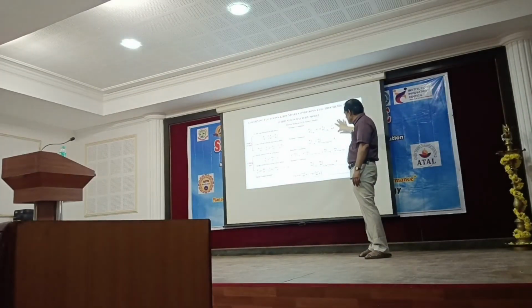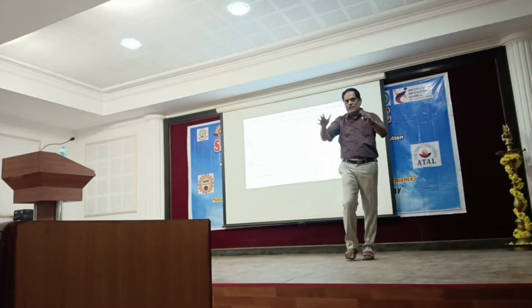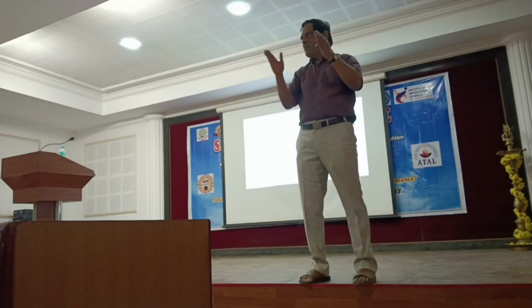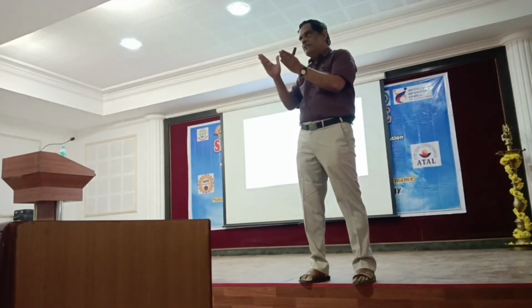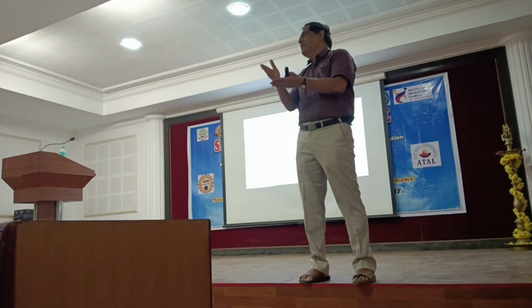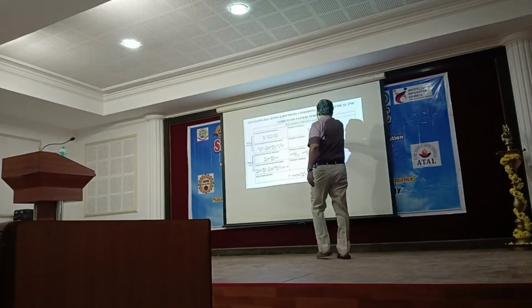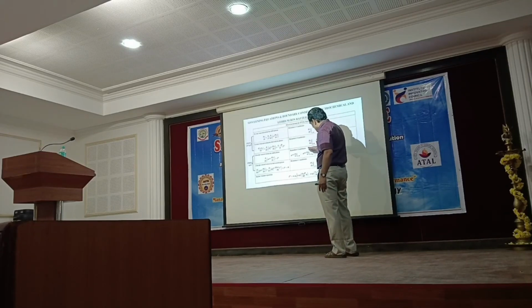For mass conservation and charge conservation, I need to know the boundary condition. When I say boundary condition, it is not an open system now. The battery pack has a particular dimension. Where it comes in, where it comes out. In the intermediate stages, is there going to be charge accumulation, mass accumulation? Everything is being accounted for. Can we impose these conditions? Yes, we are doing it in a closed system. This is what we talk about as the boundary condition.